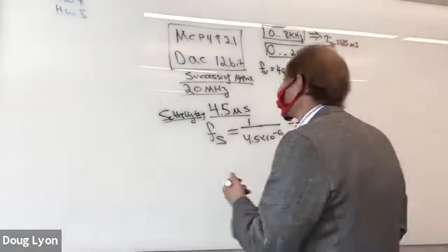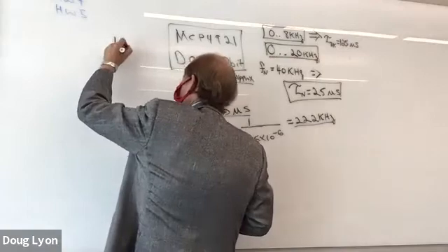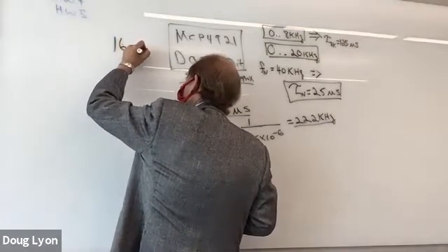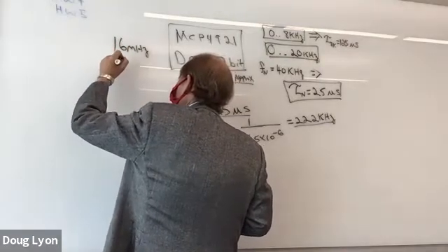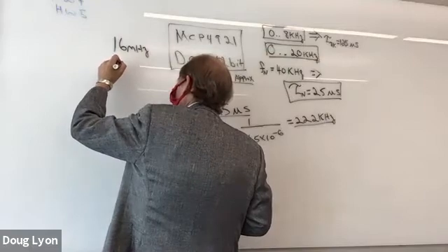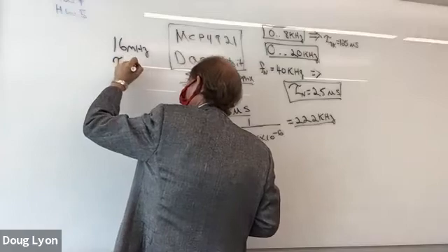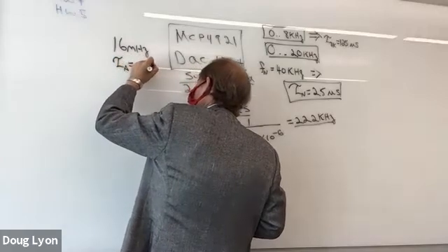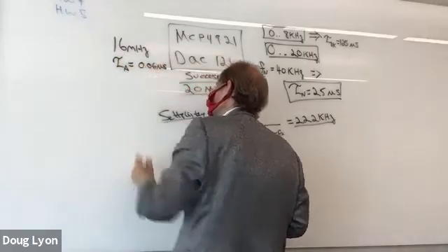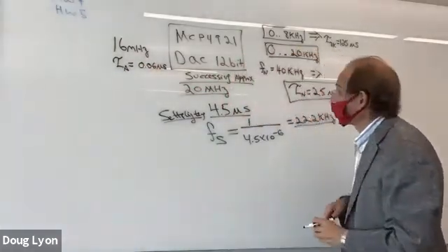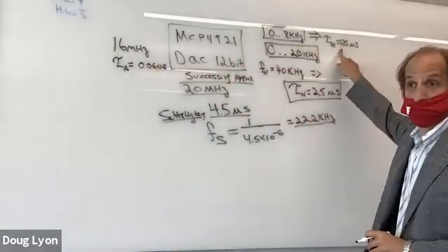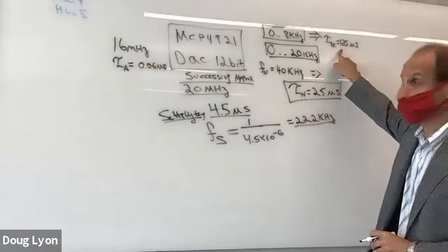That's the clock. So a 16 megahertz crystal in the Arduino is doing 1 clock cycle every, we'll call it A for Arduino, 0.06 microseconds. So Arduino is way faster than this sample rate right in here at 125 microseconds.